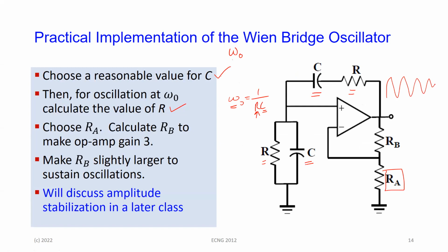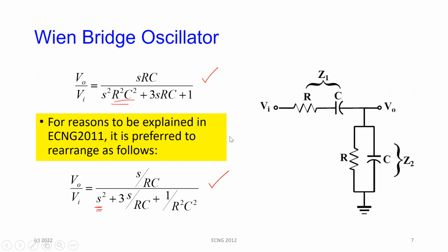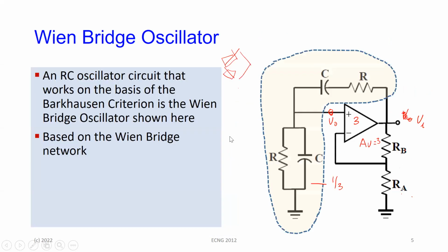All right, what we did, we started off, first off, with what an oscillator was, and then the conditions that are required for oscillation. You must have positive feedback and you must have a loop gain of 1. The positive feedback is created by having a phase of 0 or a multiple of 2 pi. And then we saw the first practical implementation of that, this particular circuit called the Wien bridge oscillator.